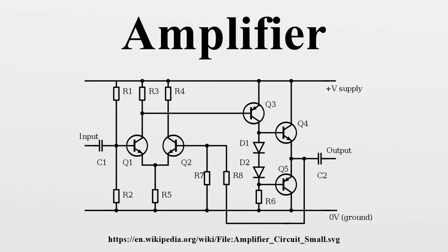In most cases, an amplifier is linear. That is, it provides constant gain for any normal input level and output signal. If the gain is not linear, e.g., clipping of the signal, the output signal distorts. There are, however, cases where variable gain is useful. Certain signal processing applications use exponential gain amplifiers.